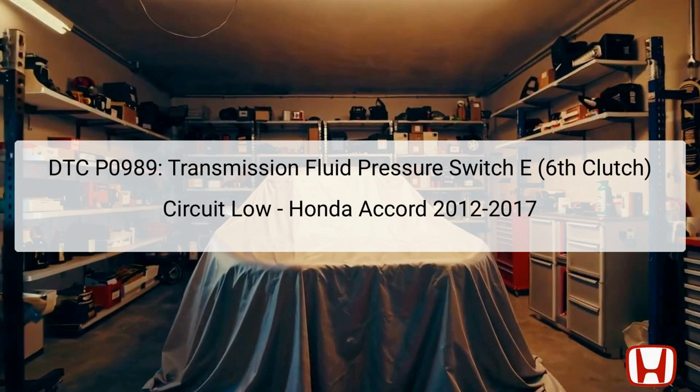If the PCM detects an inconsistency, such as when the switch erroneously remains on while not in 6th gear, it registers this error, leading to the P0989 code being stored. This code can significantly impact vehicle performance and must be diagnosed accurately to avoid driving issues.